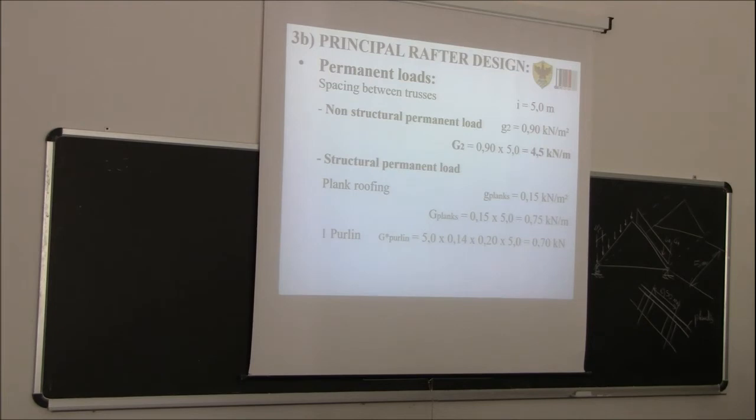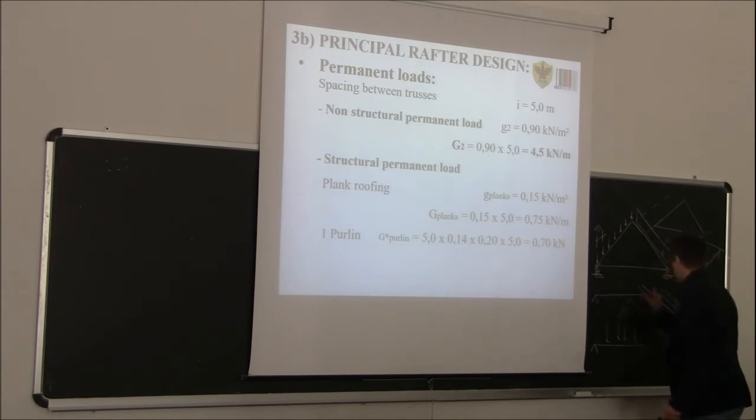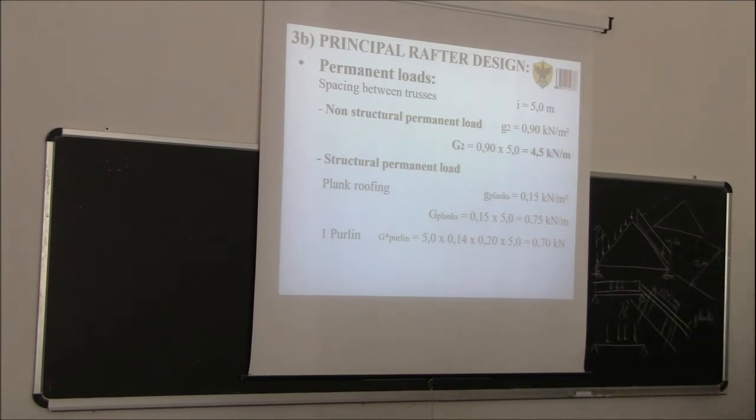Particularly, if you remember, I told you that if you have a beam with at least 4 point loads, this is, with good approximation, equivalent to a beam with a UDL. Okay? So if you have at least 4 point loads, you can transform this into an equivalent UDL. How do you calculate the UDL? Well, you sum up all these point loads and then you divide by the length. Okay? So what we can do in this case, since we have more than 4 point loads, if you check, we can directly refer to an equivalent uniformly distributed load.